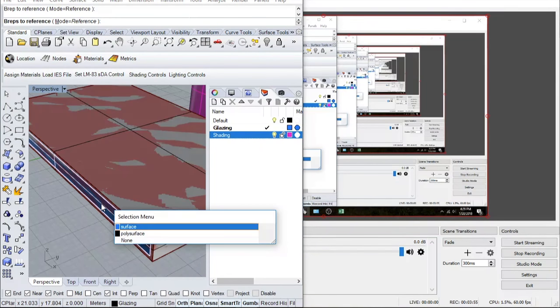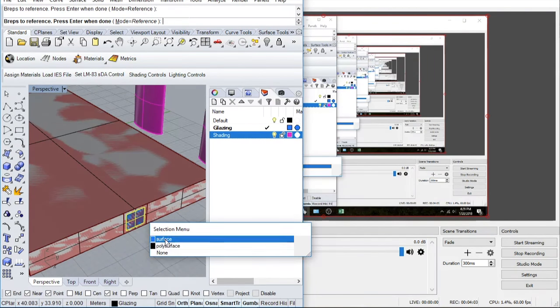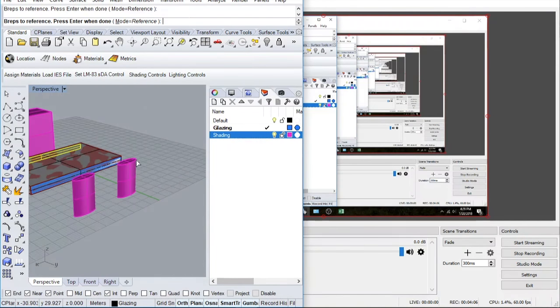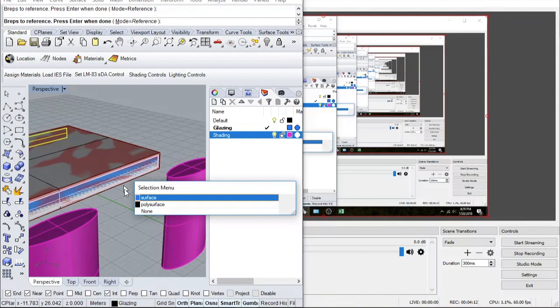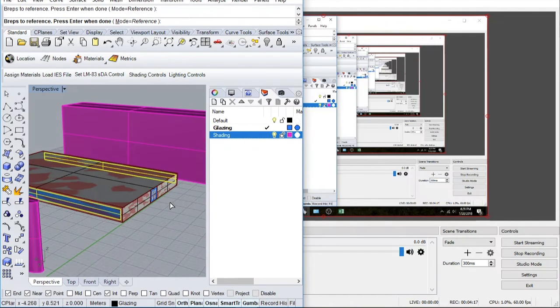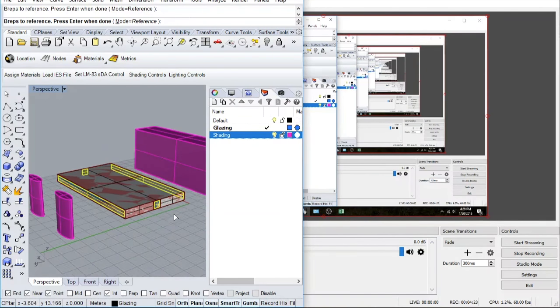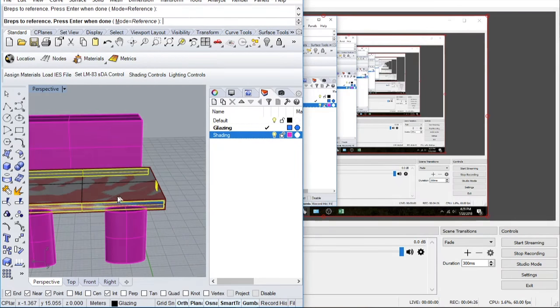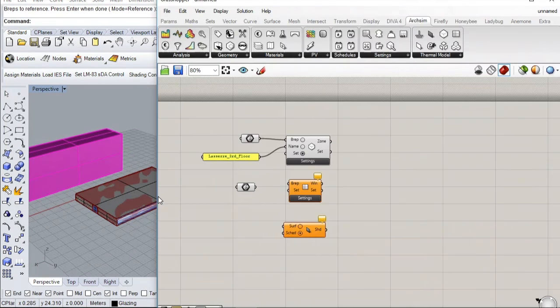And when I get back into Rhino to select these surfaces, I'm going to use Shift to select multiple surfaces. You'll notice as I go around the building, I'll have a total of 4 for all of the window surfaces I've created shown. So when I'm satisfied and I've picked all the BREPs I want to associate with this one Grasshopper component I've created, which are all the windows, I then hit Enter to return to Grasshopper.